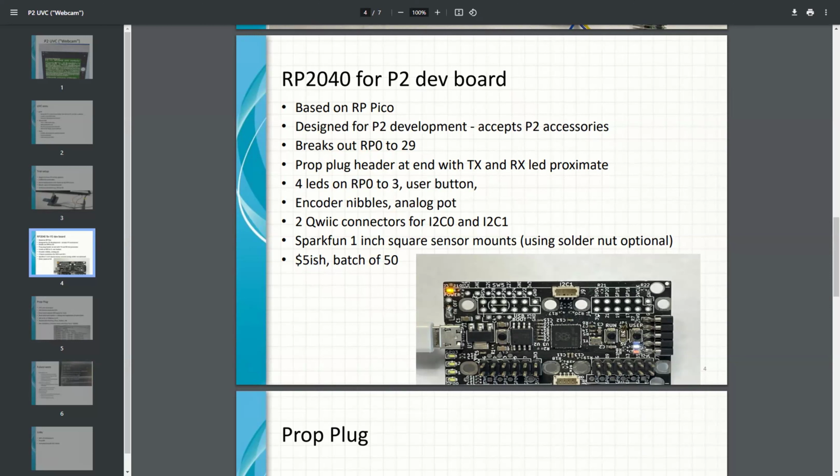So unlikely, because the actual USB isn't a standard USB controller. Normally you'd use a standard USB controller block. The P2 doesn't have it, so you have to write different USB code. There may be a need to write a hardware abstraction layer within TinyUSB, but I'm not sure it's not just bit banging underneath it all anyway. So it's something to look at whether it's possible.